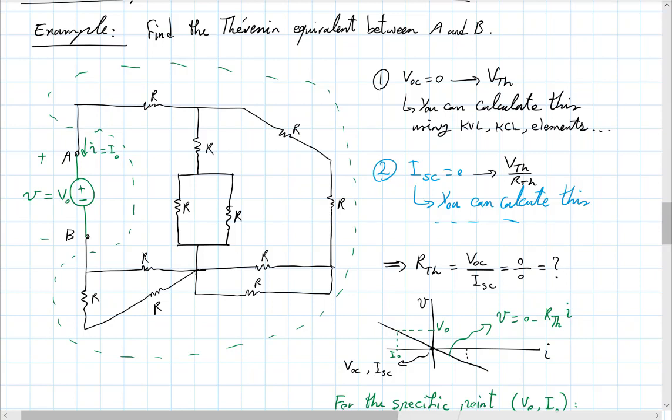And then that is in series with this other R, so it gets simplified that way by adding those up. And then these two are in parallel, so that will give you R over 2, which adds up to this R. And then that combination is in parallel with the combination of these. And then the whole thing is in series with that R, and they add up like that. And I believe you've seen exercises like this before.